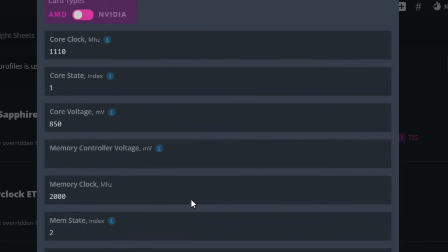Now by default these settings will return us about 29.9 to 30 mega hash on Ethereum Classic, if it runs stable. If you are wondering, I do have a video on my channel showing similar core clock and memory clock settings and what kind of hash rate you can get using the Team Red Miner.